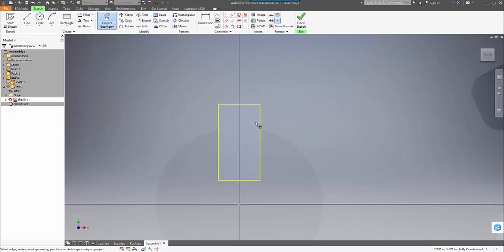We can constrain it to one edge and one surface only. Don't try to constrain it across 2 surfaces. So you'll constrain it to one surface and do a flush constraint. And so you'll have 2 mates and a flush to accomplish that constraint. But don't try to constrain to the opposite surface, because more than likely that key is going to be slightly smaller just for that sliding fit.